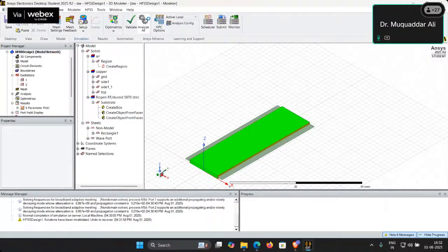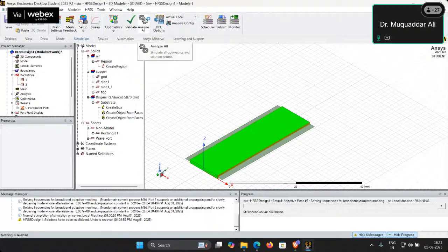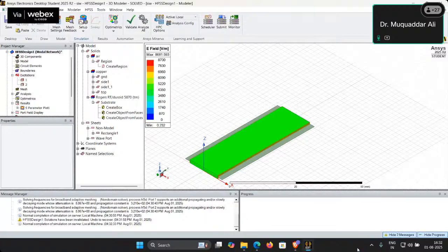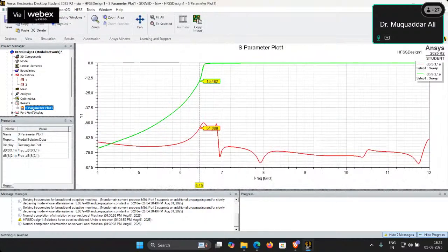So now we will be having a shift in the cutoff frequency of this waveguide. The waveguide works as a high pass filter, so it is ignoring the small frequencies. Earlier we had around 4.5 gigahertz or 5 gigahertz as the frequency. Now I am expecting around 7.5 gigahertz. Okay, so let us see. Now we can see this 6.5 gigahertz. This is the cutoff frequency of this waveguide.